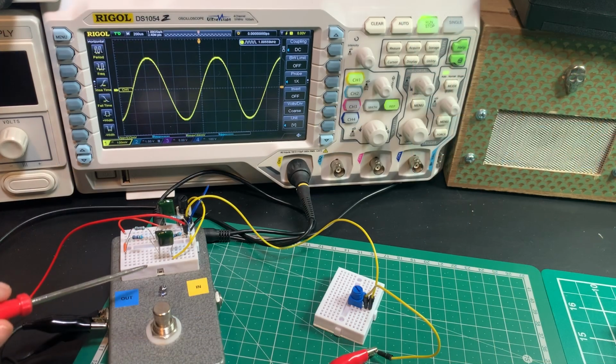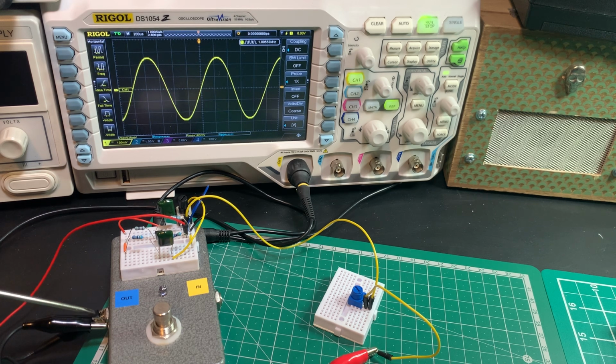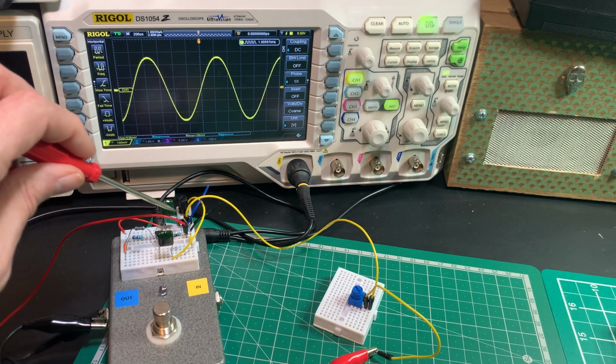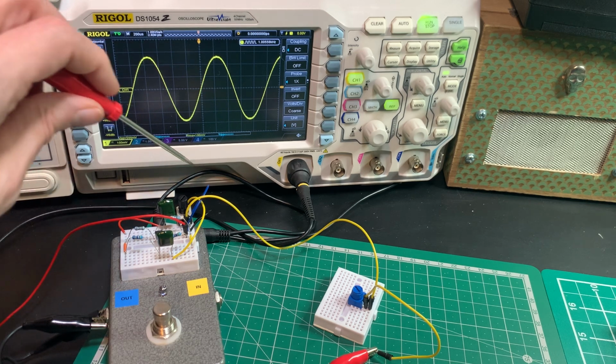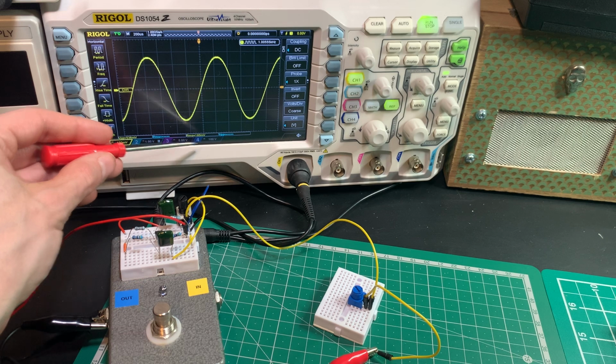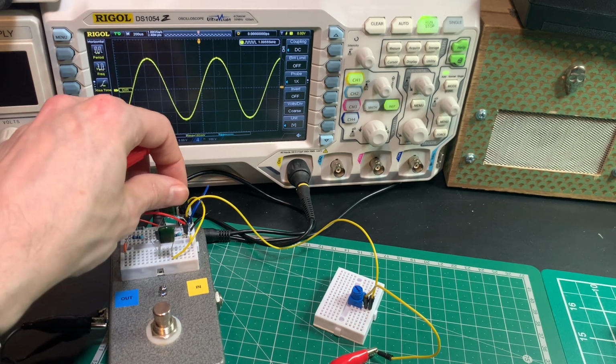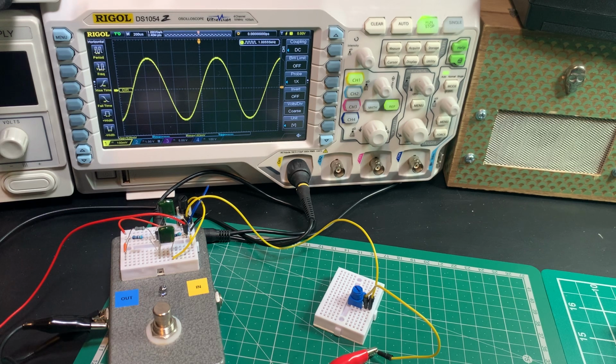Okay, very similar setup to measuring the input impedance, but note now I'm not using the input. I've got some of my grounds wired up to the output, but the oscilloscope probe is here on this red wire, and the function generator is on this yellow wire, and I've just set it up for hopefully 200 millivolts peak to peak. We just increase the amplitude till we get there. 200 millivolts peak to peak.